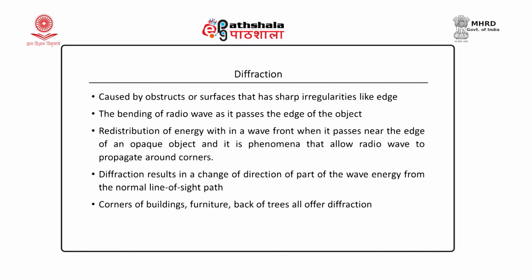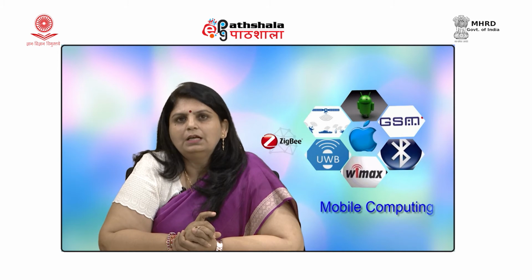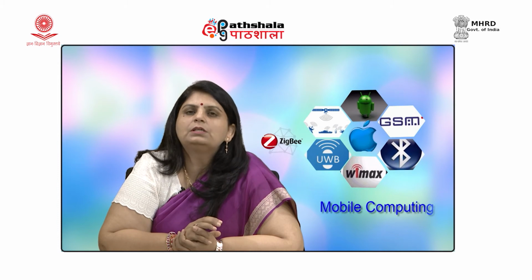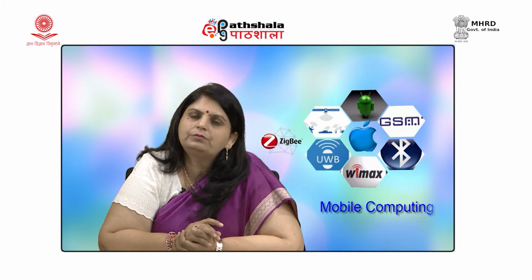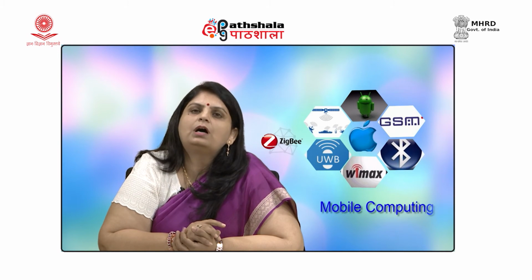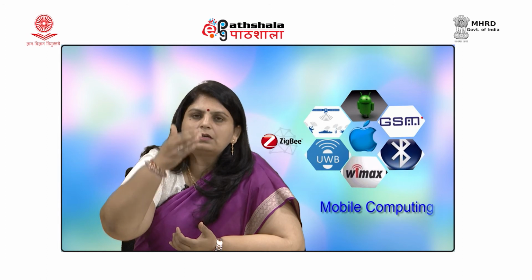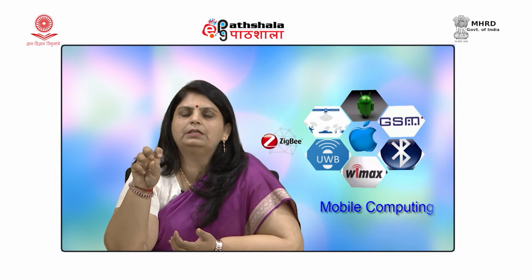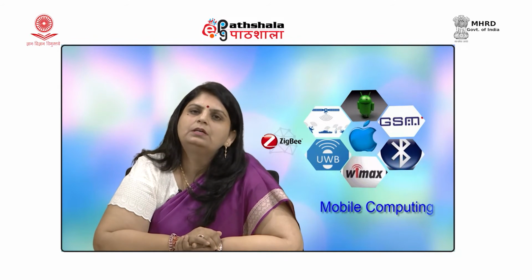Now, let us talk about another phenomenon which is known as diffraction. This phenomenon is generally caused by objects which have sharp edges. In an indoor environment, the furniture corners and the corners of the walls, everything offers diffraction. If I talk about outdoor objects, the trunk of a tree, the corners of buildings, and the edges of vehicles all offer diffraction.